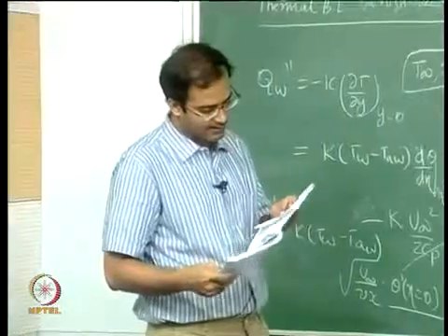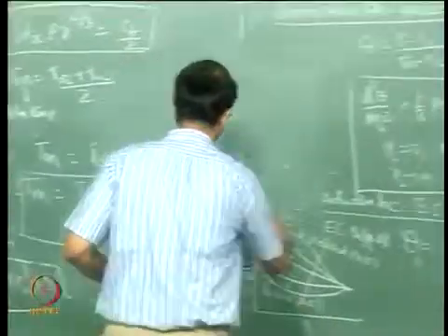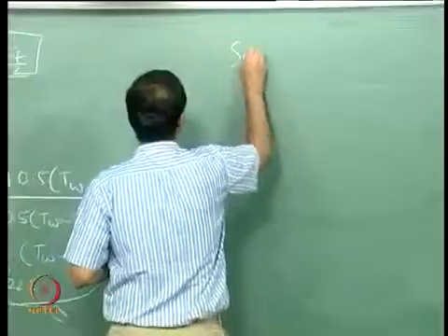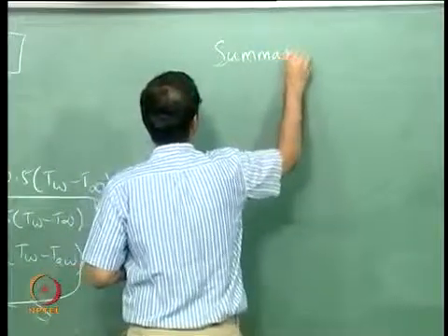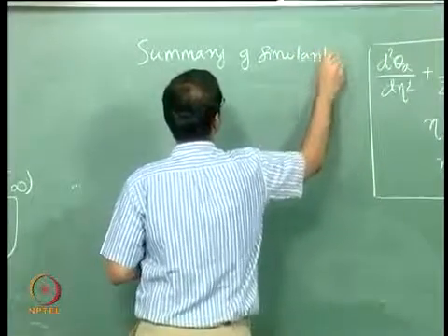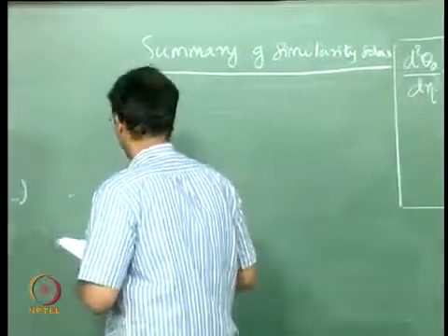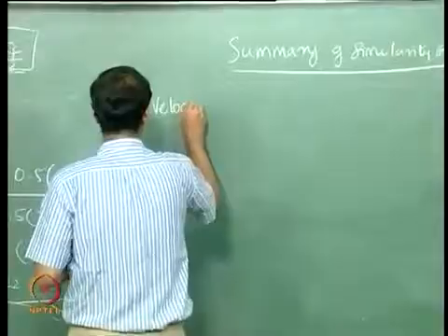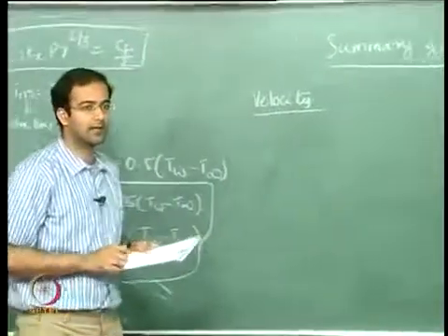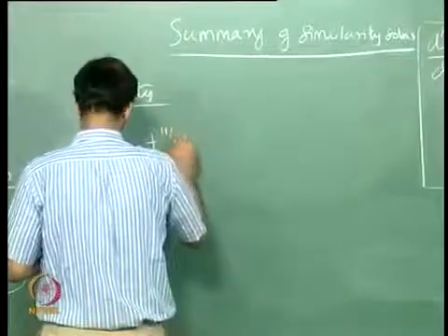If you want, I can quickly summarize the similarity solutions that we did before we stop. Okay, so a summary of similarity solutions, just 2 more minutes. So for velocity, I am just writing the global similarity solution, which is nothing but the Falkner-Skan. From there all the other special cases can be derived. So for the Falkner-Skan you have f triple prime...